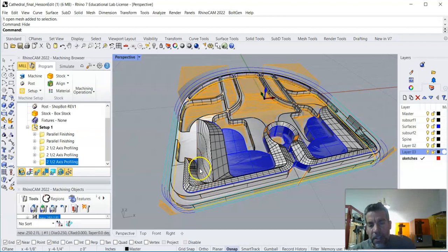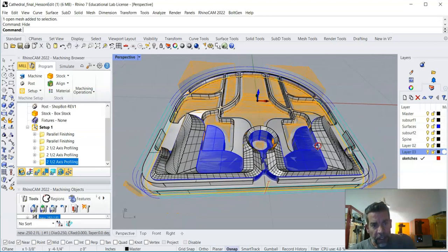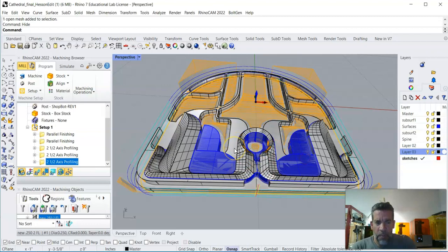There's probably some issues in there, and I can definitely tell with the degree of the curve with all the ISO curves, they don't quite match up, so that's going to help make sure that everything's watertight if we start to play with the degree of that curve. And again, there's a command called simplify curve. I'll just show you real quick.